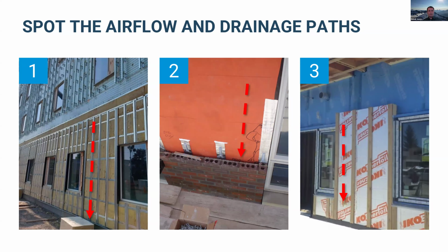Here we've got some foam insulation that's screwed on with these battens, these vertical battens. And we've got our airflow path, or our drainage path, on the front face of the insulation there. You may get some limited drainage behind the insulation. We do see a membrane there, but not much in the way of airflow. It's going to be pretty tight against there.